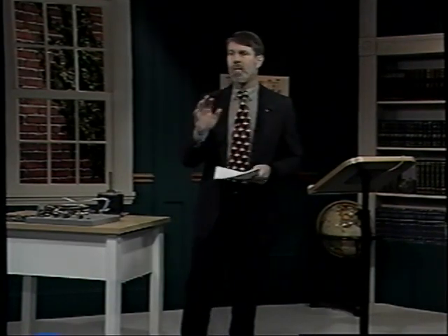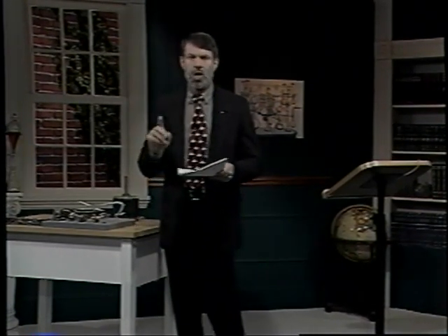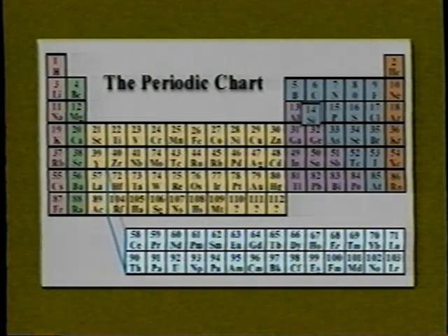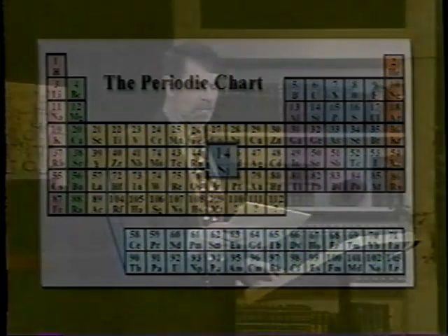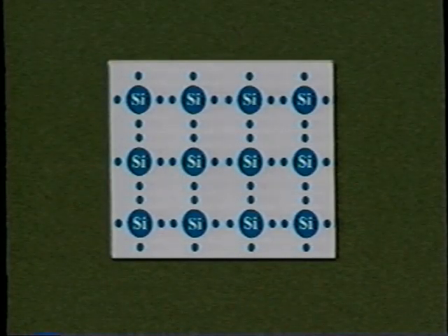First of all, you should know that semiconductors conduct electricity, but not very well. Most modern semiconductors begin with a crystal of the element silicon. That's element 14 on the periodic table. Now, silicon, when it's electrically neutral, has 14 protons and 14 electrons. So it has a half-filled outer shell. 4 of the 8 possible electrons are present in the third shell. So silicon's strategy, just like carbon, which is above it in the periodic table, is to find 4 more atoms.